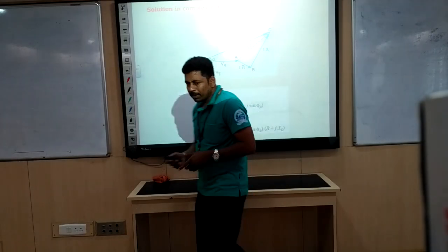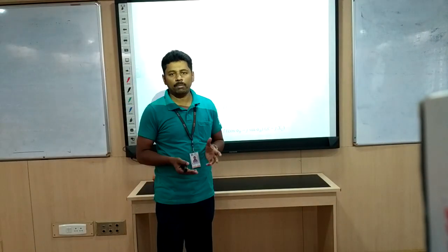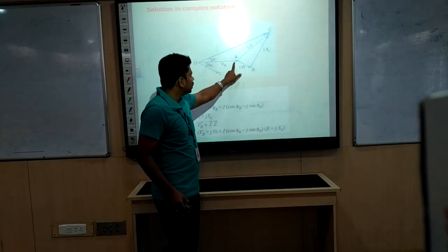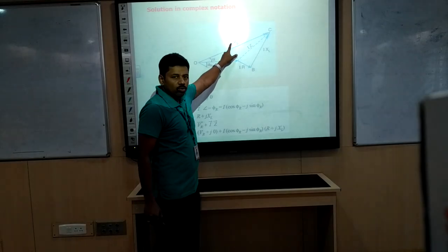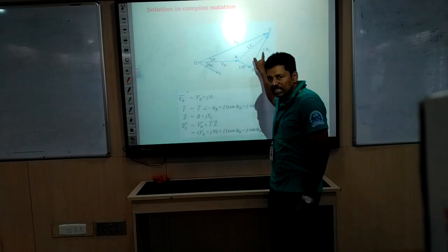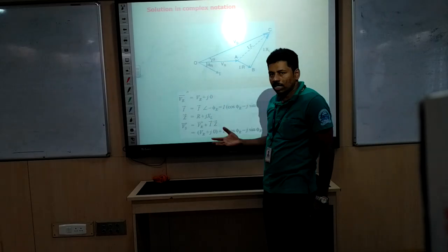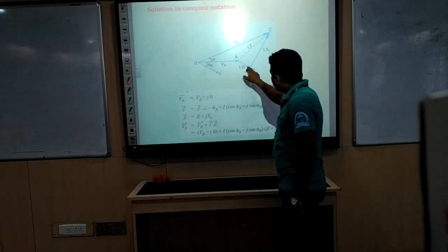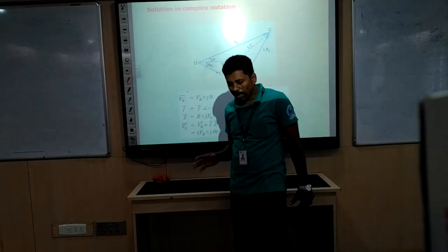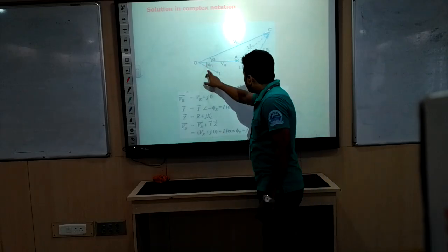In order to represent all these parameters, the sending end and receiving end parameters, we normally draw the phasor diagram. Taking Vr as reference, to reach Vs, the sending end voltage, there are two drops. One is the IR drop and the other is the IXL drop, where IR is the resistive drop. Is is equal to Ir is equal to I, we assume. This current always lags by an angle phi r because most of the time the load connected to the transmission line is inductive in nature.